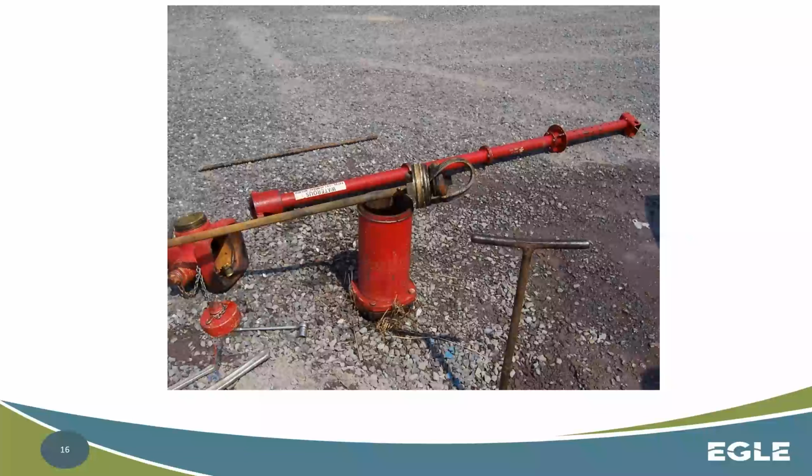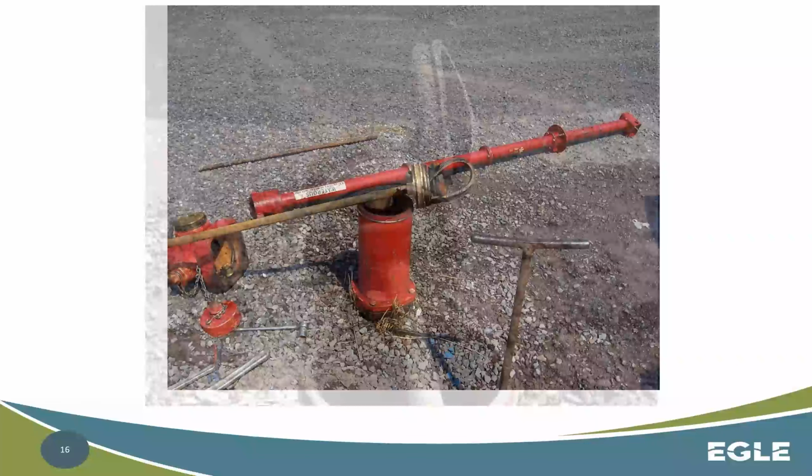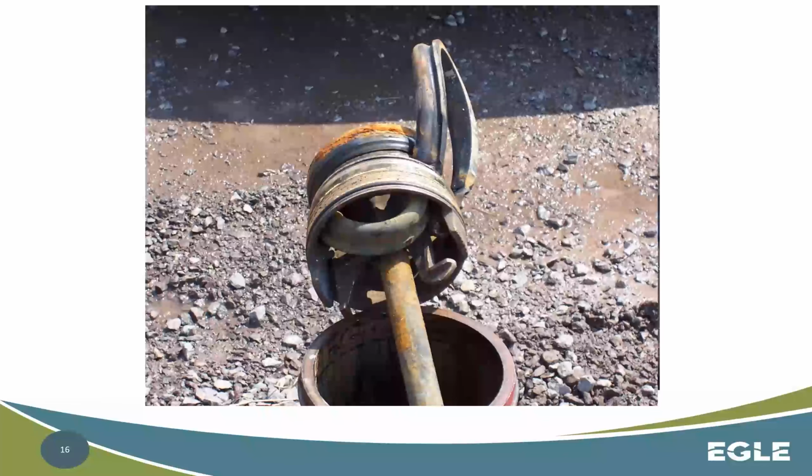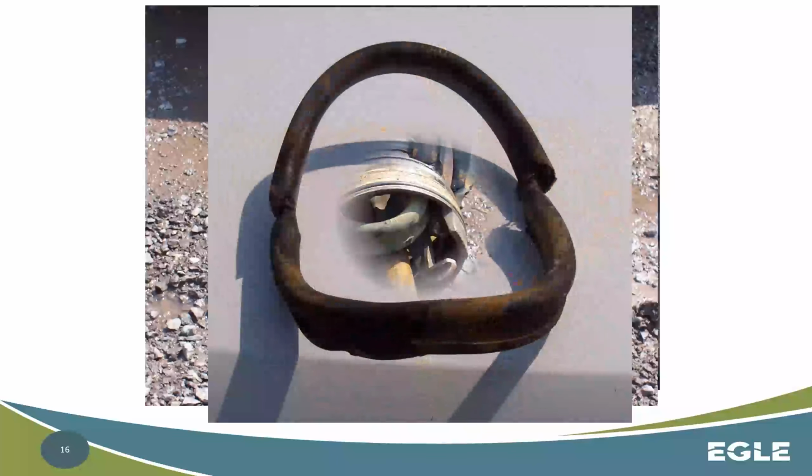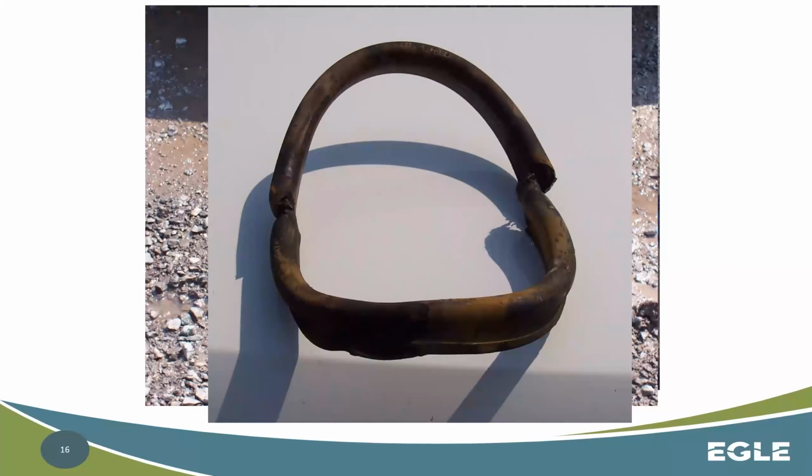The municipality was very quick to blame the firefighting team for breaking the hydrant, is what they thought, because they couldn't get the hydrant to turn off. As much as they would crank and try to do stuff, it just would not turn off. Through further inspection, they started seeing that there's actually something stuck in the valve stem that's forcing the valve to not be able to seal. And after they got that removed, they found out it was a stray gasket from water main installation. That's where that extra gasket went.